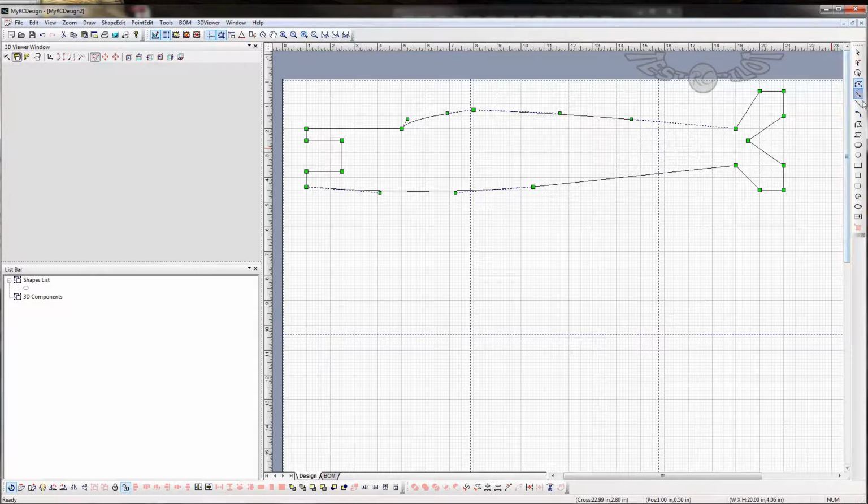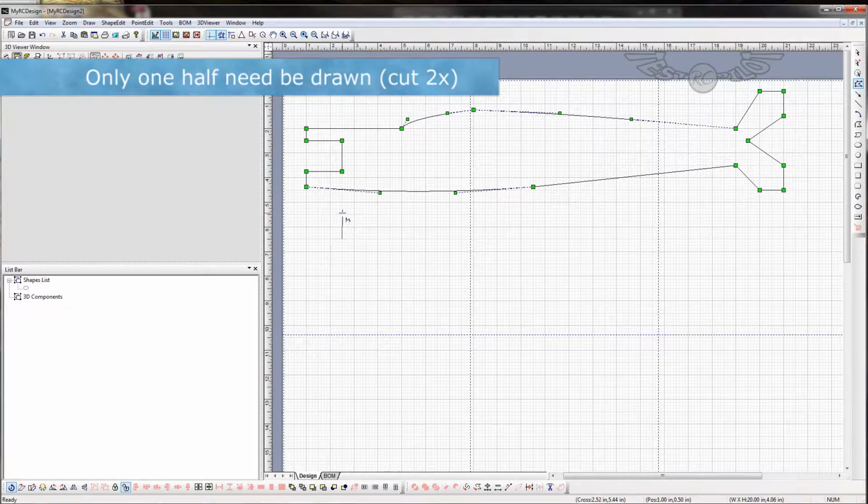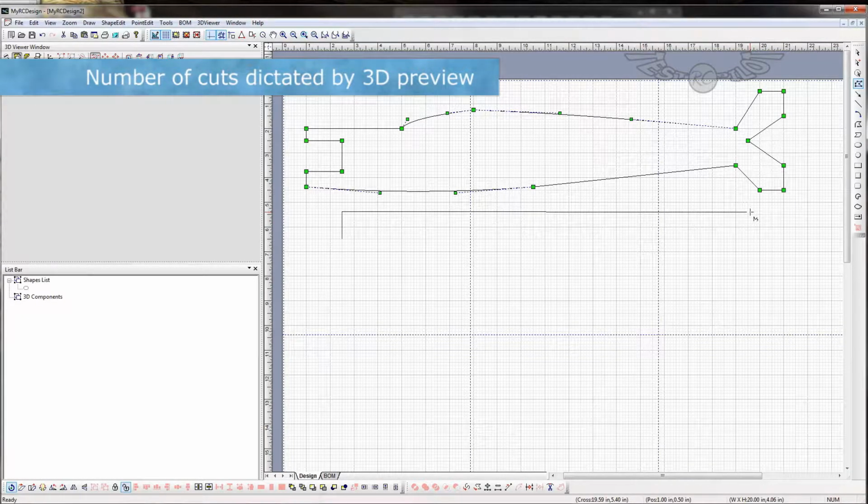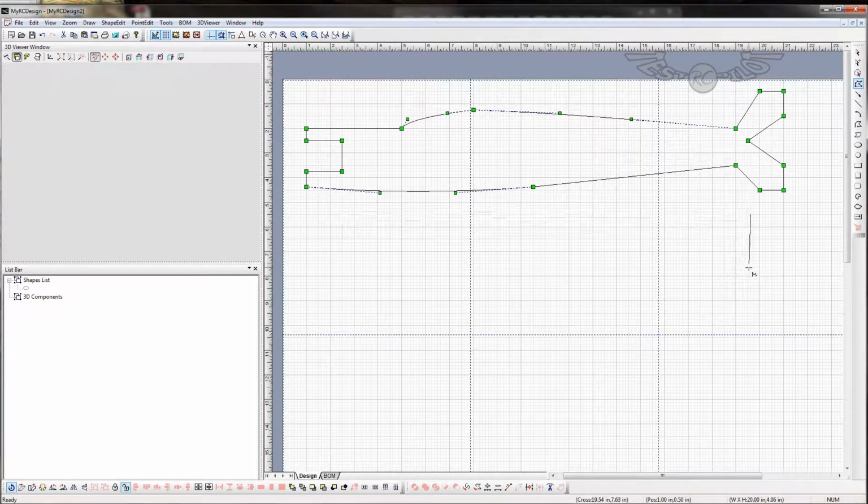Just for the fun of it, I'm going to go ahead and create a basic cruciform, just really quick, just knock something out. What you're going to do is do it in 2 halves, and it helps to do it right below so that you can line everything up. So the motor mount will be right about there, and this goes straight on back to right where the elevator will rotate. Okay, then this will come out, and this will be the stationary part of the elevator, not the part that actually rotates. So it's really just the vertical stabilizer.